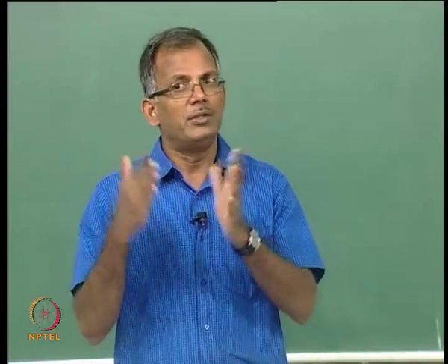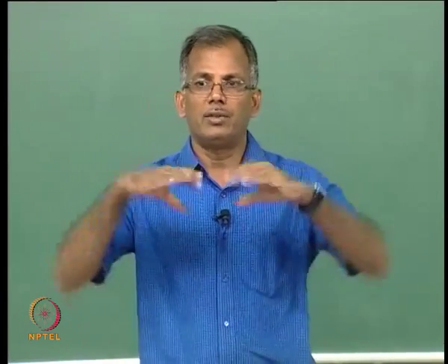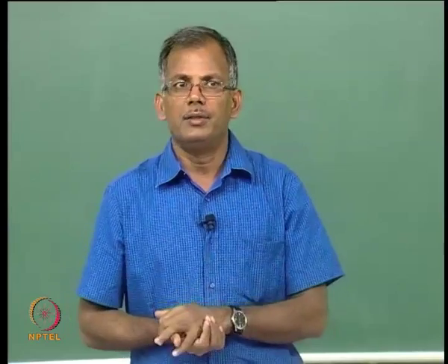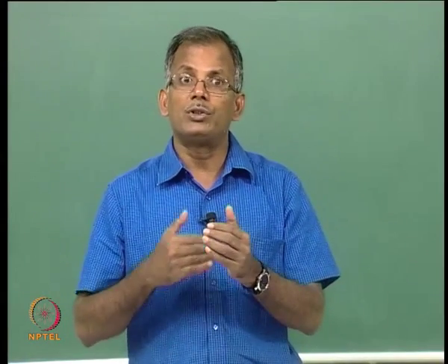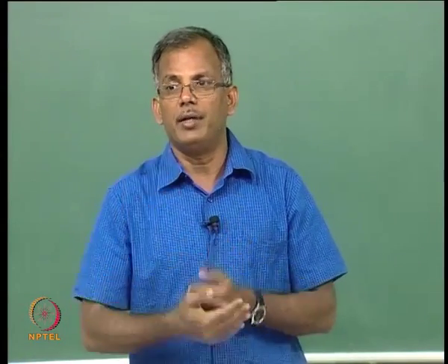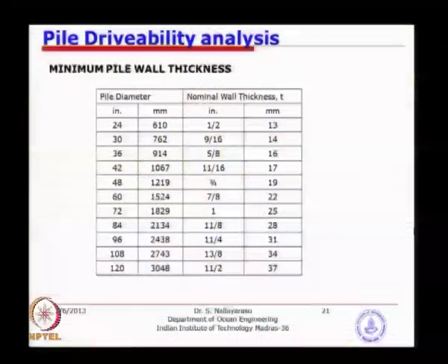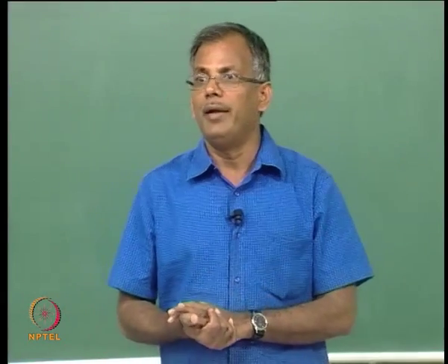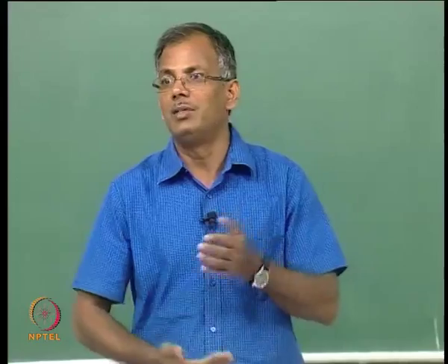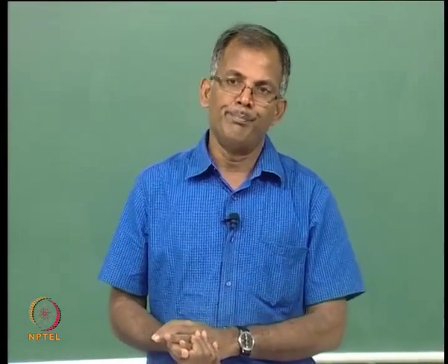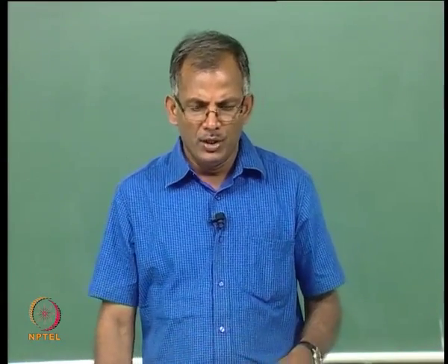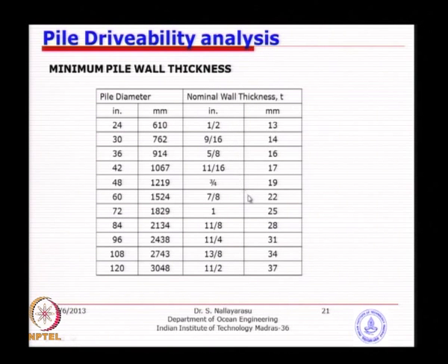Of course, failed means it could easily come out because the pile started buckling and the direction could change, but there is an overstress, for example the stresses are beyond yield, especially if you have not used a pile driving analysis like what we are going to learn. If you have used a dynamic pile driving formula, there is no way that you can find out the stress levels at various locations below seabed. That is why these recommended values have been removed from the code, but still we could use them as a guidance just to understand what actually we are looking at.